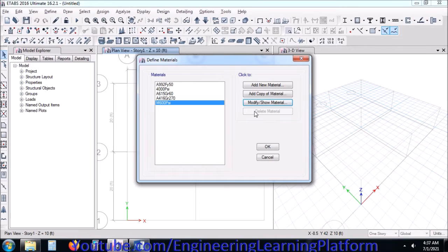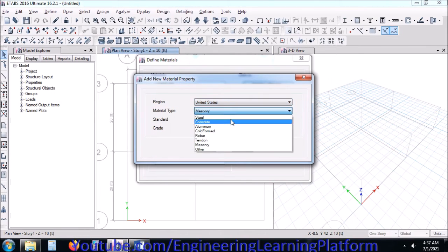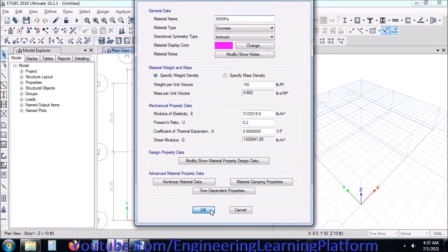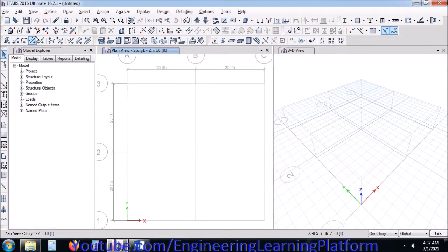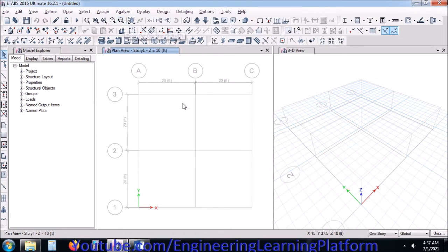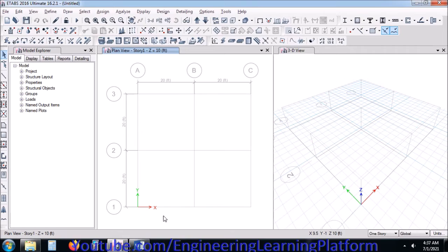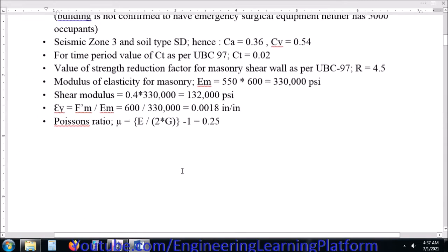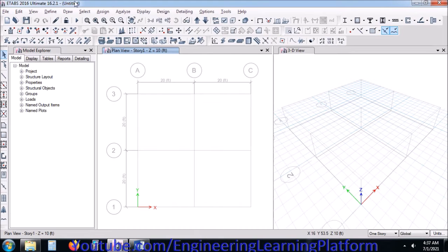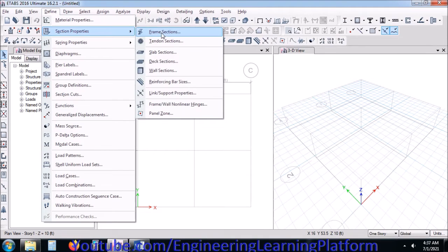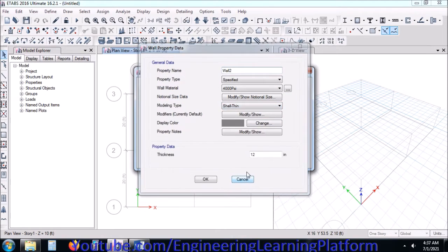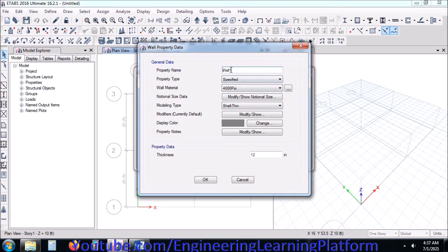The compressive strength of the concrete. Since we will be using the band beams and the reinforced edges, it would not be right to call them columns as they would be too slender and small sections. So I'll be calling them reinforced edges of the wall or reinforced interlinks between the walls, as it may be required that we will be providing these reinforced corners or portions of the wall midway of the wall. So let's define the wall section of the masonry.